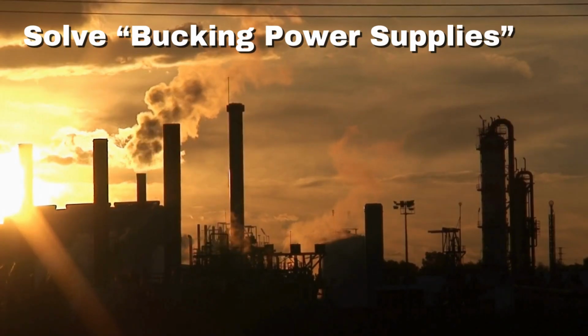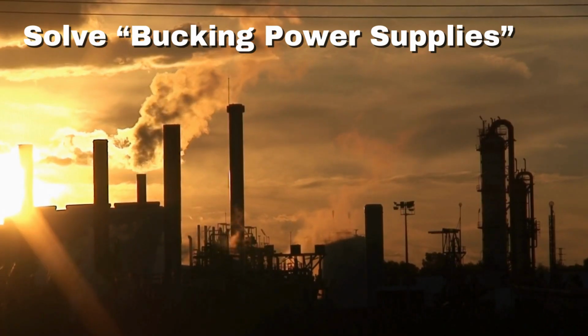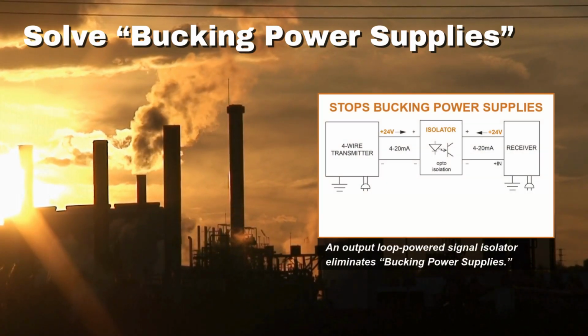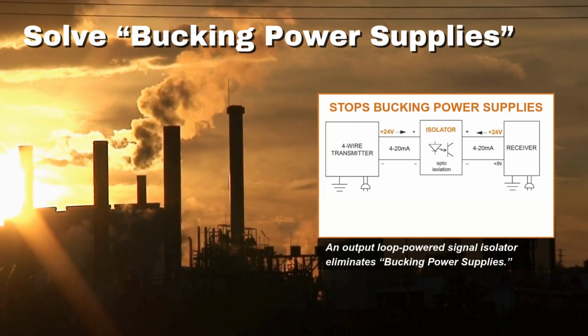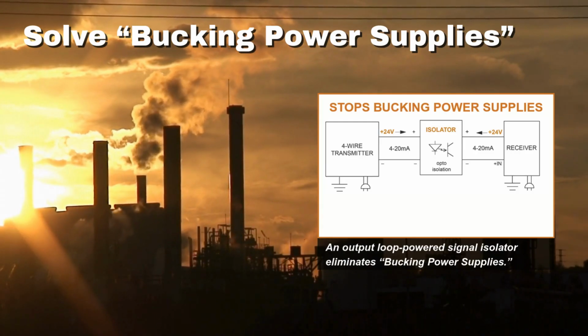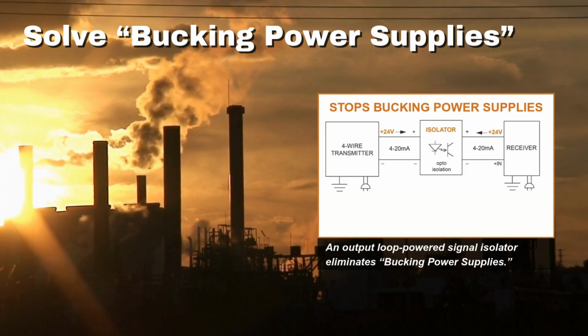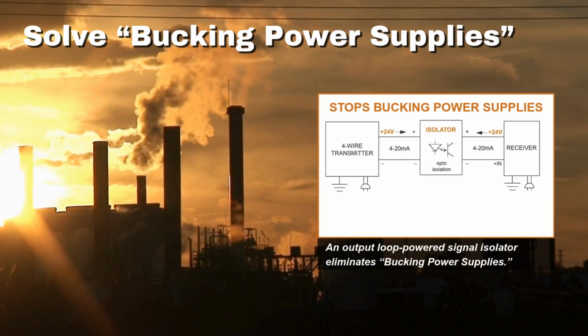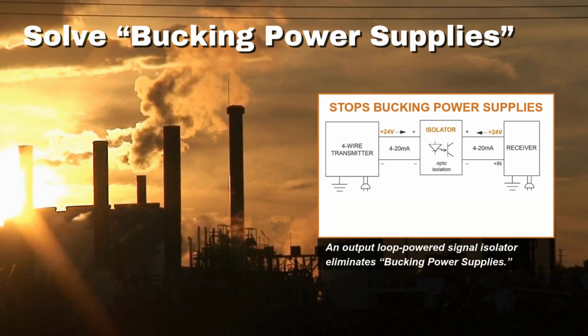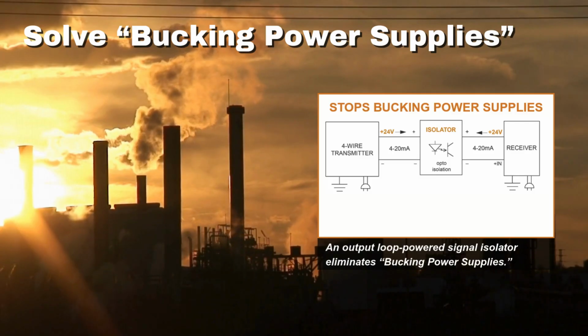Beyond sharing signals between systems, isolators also solve power conflicts that can occur inside the loop itself, especially when powered devices are connected where they shouldn't be. Some BPCS systems use lower-cost 4 to 20 milliamp input cards that must power every loop connected to them. This works fine with loop-powered transmitters.